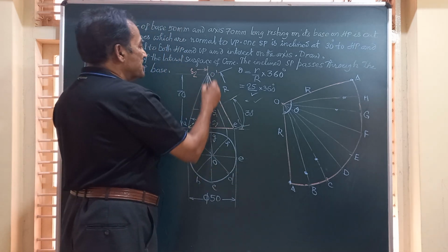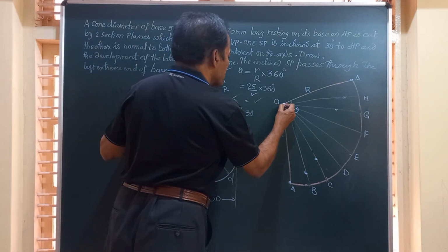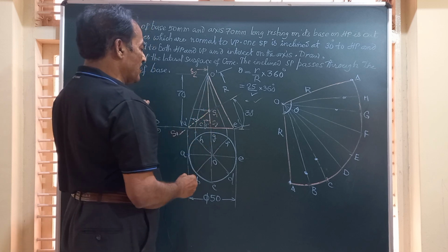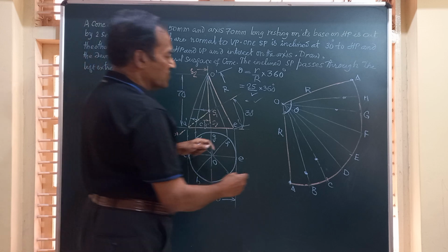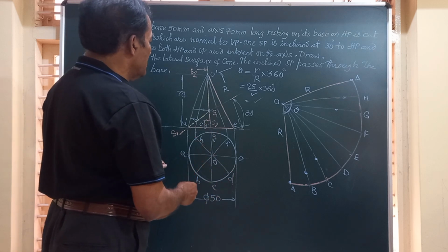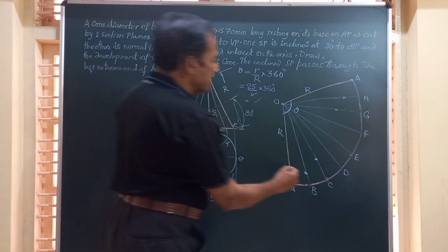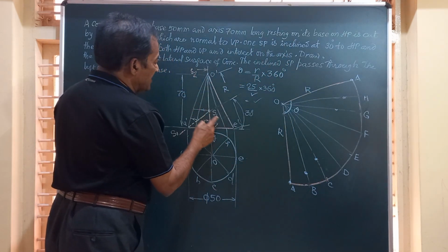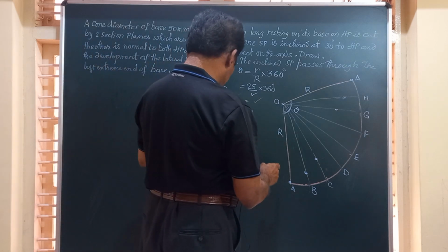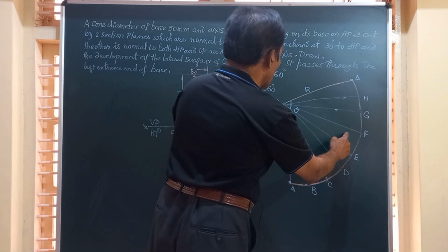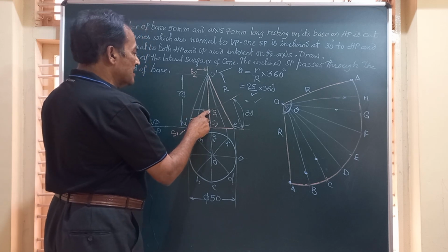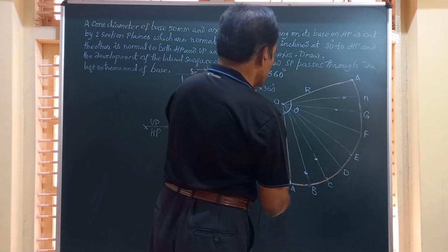Next, friends, you have this vertical section plane which is passing through O. So O is going to be one of the points. And then these two are intersecting at the midpoint of the axis, that is on OC and OG, that I have marked, friends. Now, friends, we can see here that OE is completely to be retained, and here we have got OD and OF, they are also not touched by the section plane. OD and OF are to be retained, and then you have got OC and OG cut up to here.